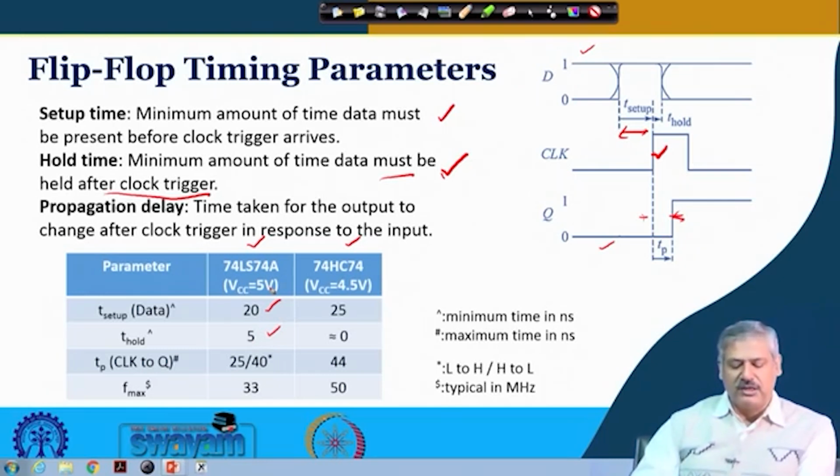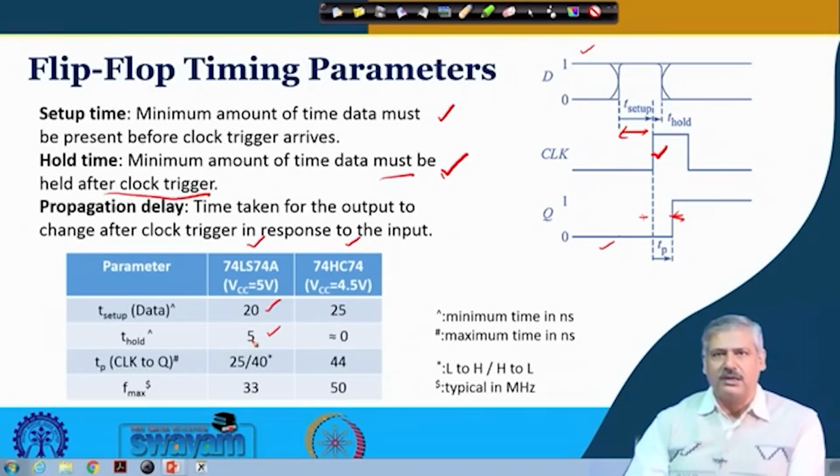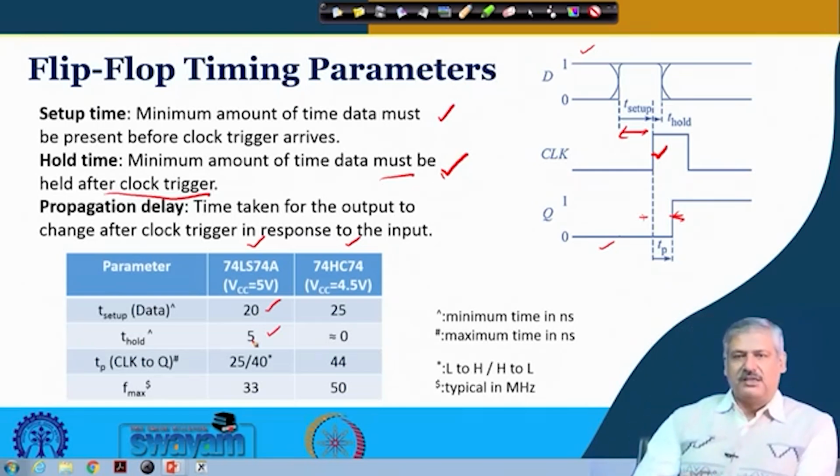These are the 7474, 74LS and 74S. L means low power, so higher resistance values. If it is only S for Schottky, which we have seen in the logic families, then the resistance values will be standard and the time will be relatively less. These are just the order of values; for different families with different realizations, you will have variation around them.